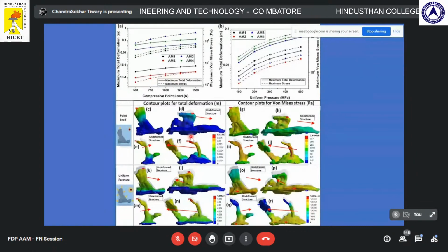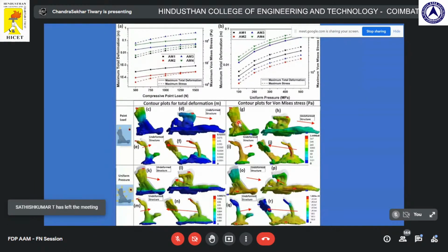So this is strain distribution and this is stress. And you can see the stress is really localized just because of the complex topology. It cannot transfer even to the next region. And that explains the first question, that ants have this topology to protect themselves from exterior point load.